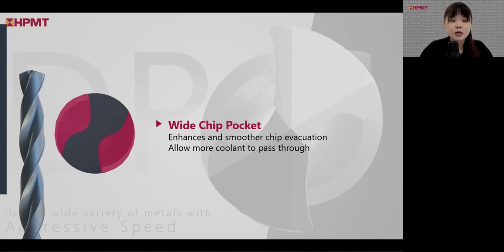All right. So with this wider chip pocket size, it will definitely help enhance and give better chip evacuation. Also, because the space there is wider, when you are trying to flush coolant through, it allows more coolant to pass.